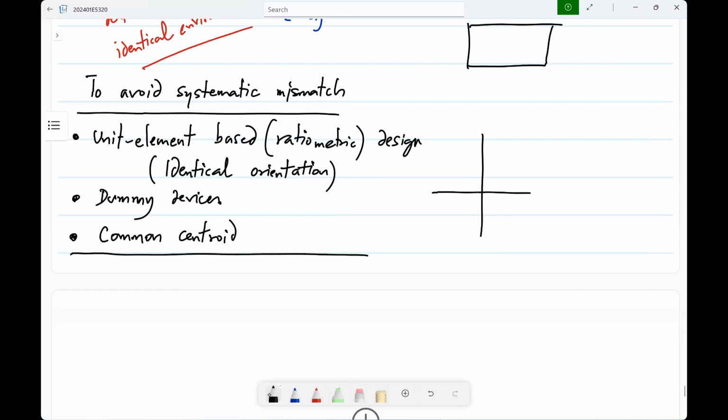If you have two wires crossing, they'll be either in different metals, or even if they are in the same metal, the crossing part has to be in a different metal. They can't be in the same metal. So there will definitely be asymmetry. The more crossings you have, the more connections have to travel through different metals, and you can't make them exactly symmetric.